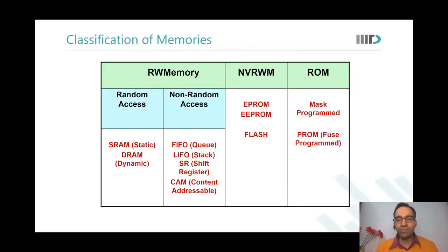Now what about last in first out? I've already mentioned, we use it whenever we want to implement stacks in our system. We use a last in first out kind of memory. What is happening in these last in first out and first in first out is you do not really look for an address from the user. You maintain an internal pointer which addresses the locations that need to be addressed.